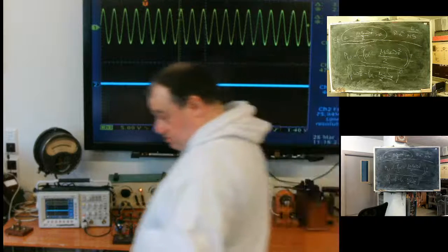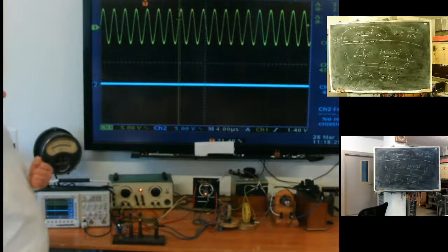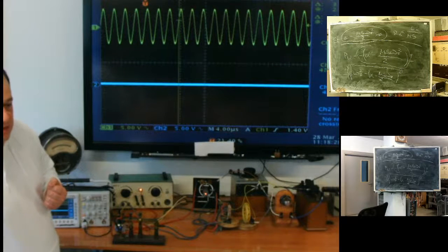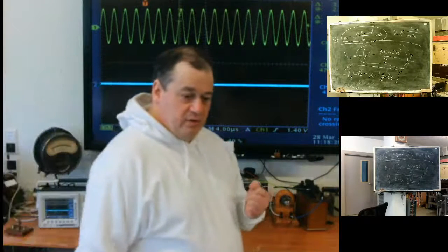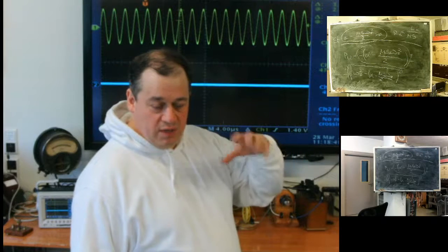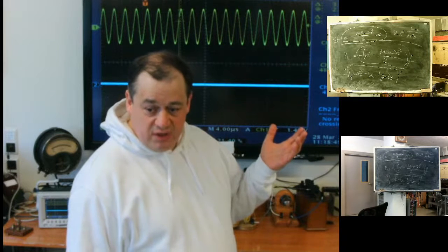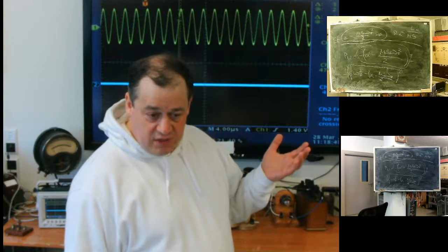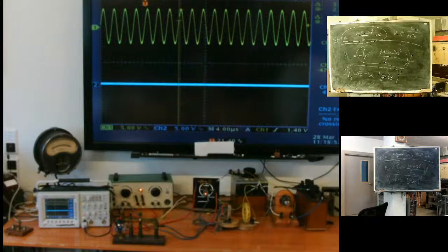Because the system wasn't stable. The problem was, for example, when we need to keep voltage constant, voltage stabilized. If the load voltage decreases, we need to amplify. It's a positive coupling. So a voltage stabilizer is potentially unstable. We need to take measures to prevent it from oscillation.